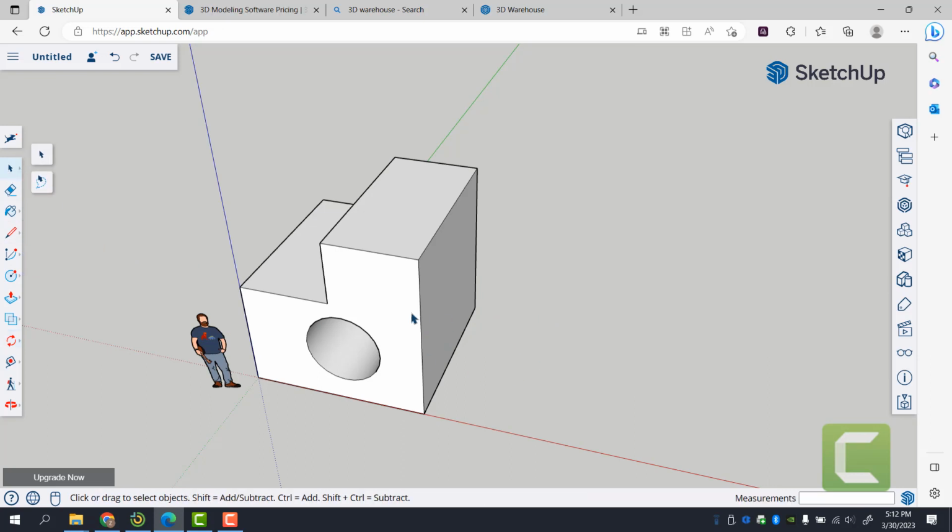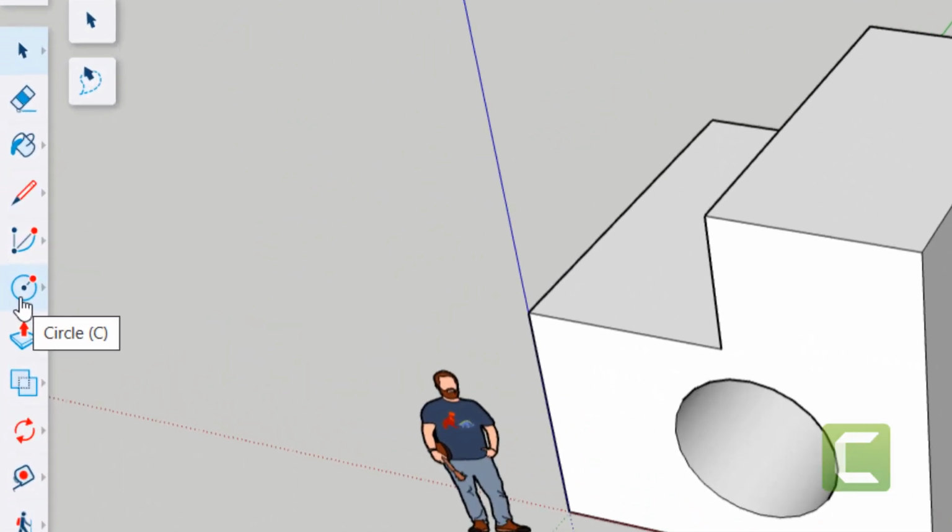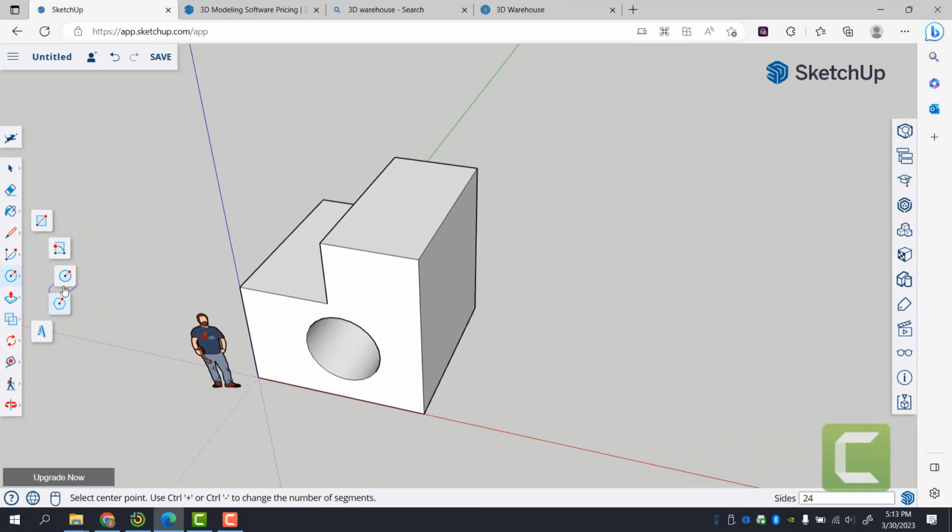Now, the next thing I'm going to do is, as you can see, the moment I draw an additional square or shape on top of a three-dimensional object, it immediately becomes a part of that object. Give you an example. I'm going to use the hexagon tool, and I'm drawing this on the face. And when I push pull, notice how it's instantly part of that original surface that I drew out from.